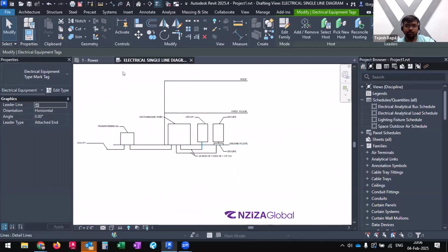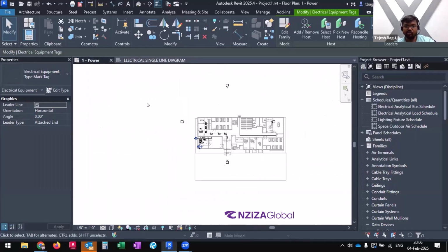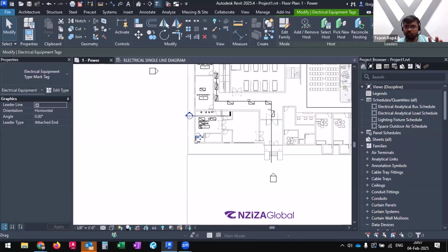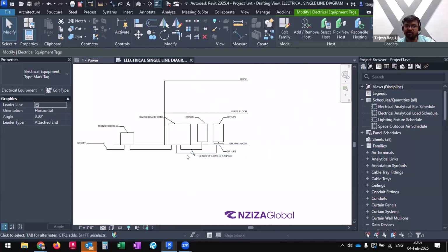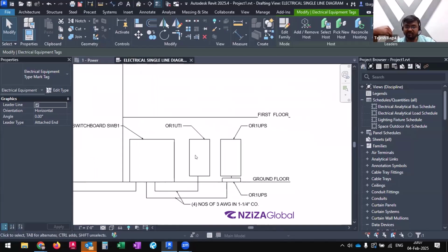All right. So he will check the location of the given transformer. He will check the site conditions, because many a time the underground conditions are not known during the design phase. He will check on field what is going on, maybe dig a trench and see if there are any existing utilities that might need to be rerouted, and so on. And then based on these two pieces of information, the location on the floor plan and what we have seen over here, he will usually send us the shop drawings for approval. Once we approve it, only then will they start ordering.